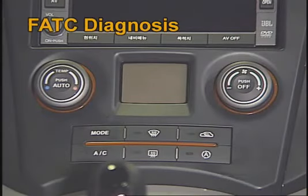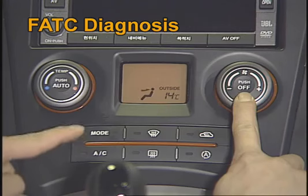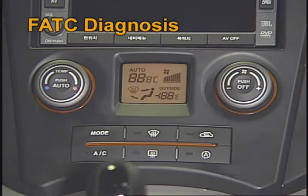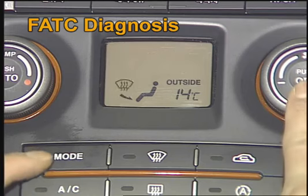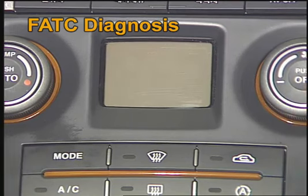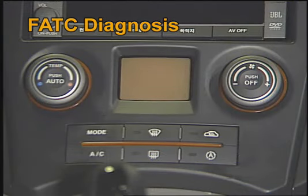Now, let's study about the self-diagnosis method. Press the off button of the FATC control panel and then press the mode button at least 4 times within 2 seconds. Then, the screen of the control panel blinks 3 times and self-diagnosis starts. As the result of the self-diagnosis, if there is any defect at the temperature screen, the error code will be shown.